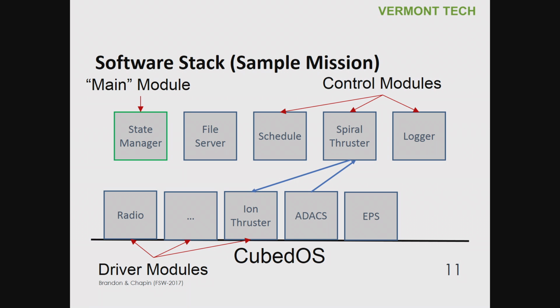And that exposes all 3 axes of momentum in the spacecraft to the action of the thruster. And by appropriate timing of when you actuate the thruster, you cancel out the unwanted components and put the momentum component in where you want to dump momentum from the momentum wheel.